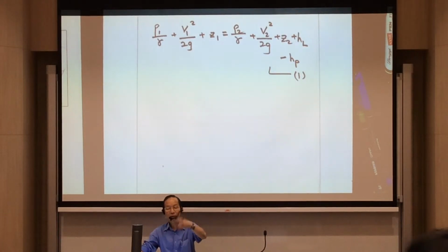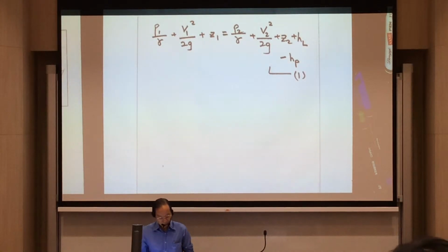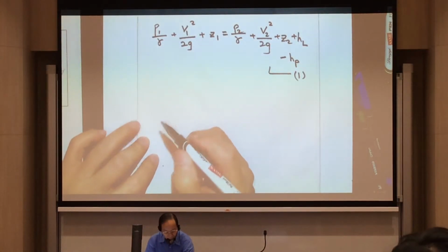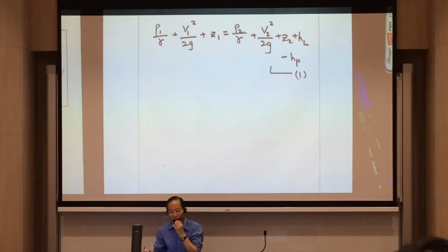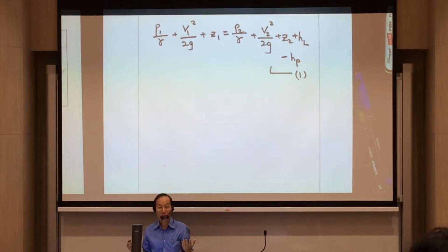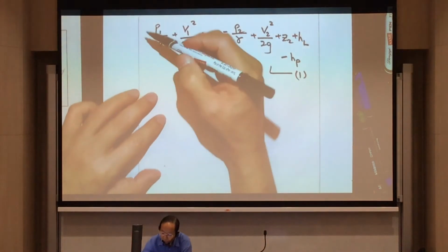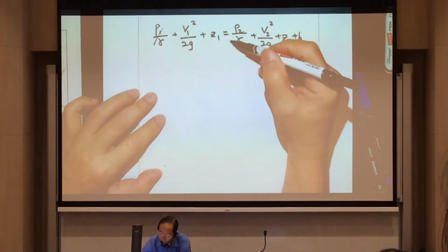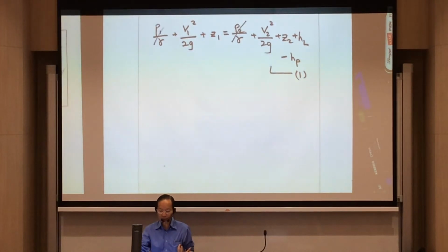Okay, let this be interactive. What is P1? And what is P2? They are atmospheric pressure. Okay, so they are actually gauge pressure basically. So this will cancel, this also cancels. In fact, gauge pressure is considered as 0. Okay, gauge pressure is considered as 0.